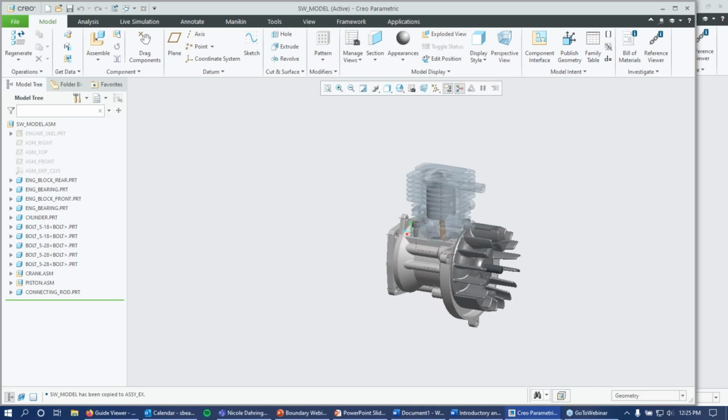Is it possible to skip creating a part first in an assembly? It seems like an extra step. Can you create a shrink wrap in an assembly without creating a part of the assembly first? I think I kind of covered this. I think the answer is no there. As far as creating that feature in an assembly, a lot of features can be created in assemblies, but many cannot, and they're specific to parts. As far as I know, there's no way to create a shrink wrap feature native to an assembly file.